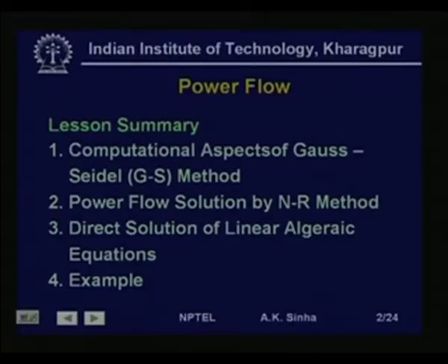Well, in this lesson we will start with some computational aspects of the Gauss-Seidel method. Then we will talk about power flow solution by the Newton-Raphson method. We will then talk about direct solution of linear algebraic equations, as we will find that the Newton-Raphson method finally boils down to solving a set of linear algebraic equations, and then we will take a small example of solving these linear algebraic equations by the Gauss elimination method.